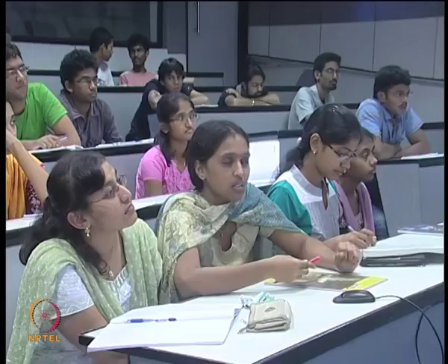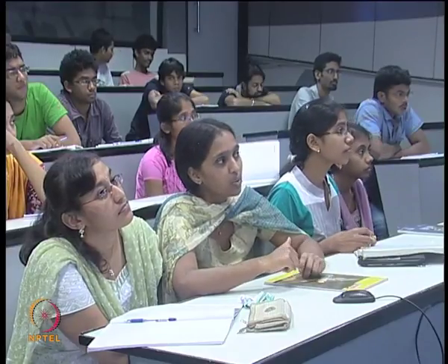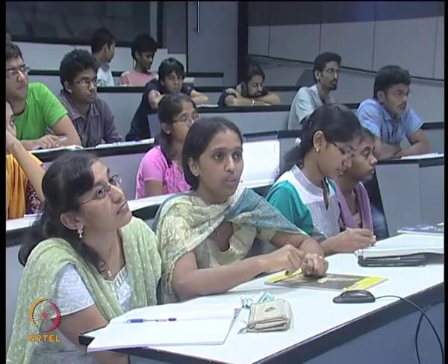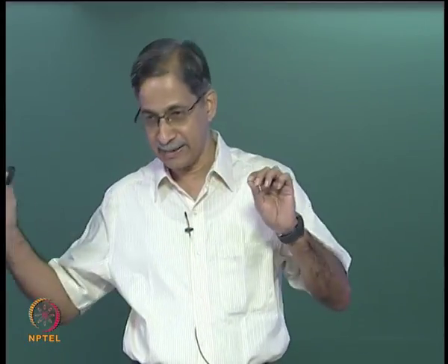Local coordinates. One axial degree of freedom and 2 moments in element 1. Right. But element 2 has 1 axial degree of freedom and 1 moment only. No, they are all frame elements. All are identical. All have 1 star as the axial, because there is going to be an axial force in that element.